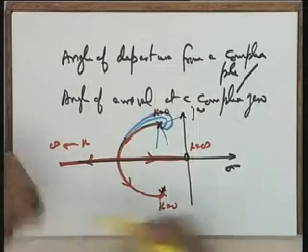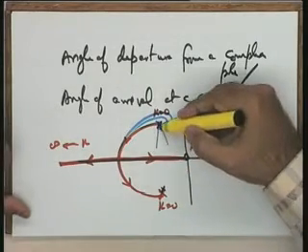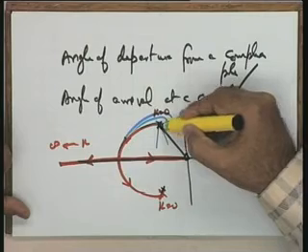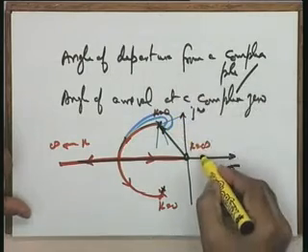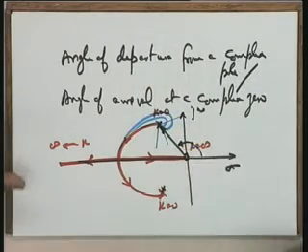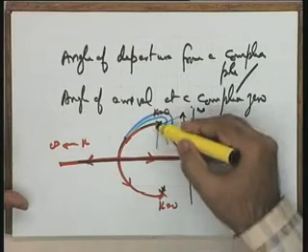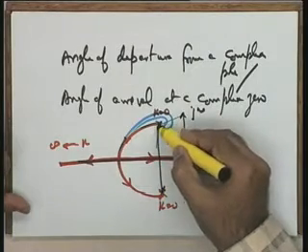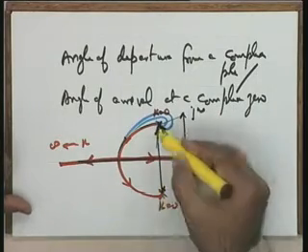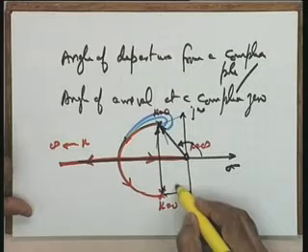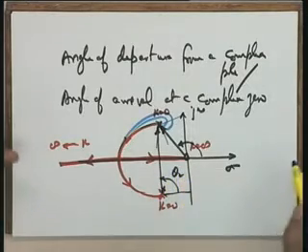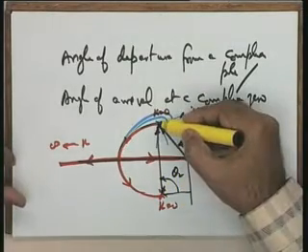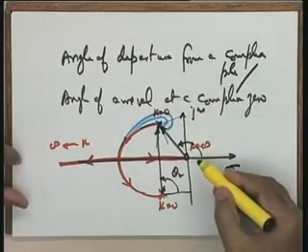The process is like this. You get the angle contribution at this particular pole. Let us call this theta 1 due to this zero. You get the angle contribution because of this pole at this point, and let me call this theta 2. The net contribution at this particular pole is how much, please?